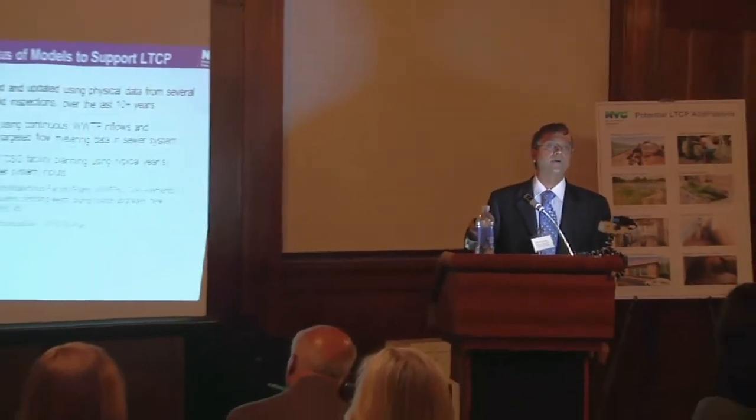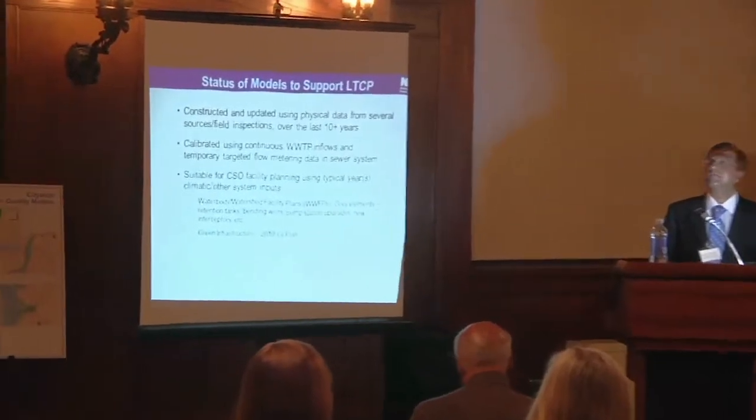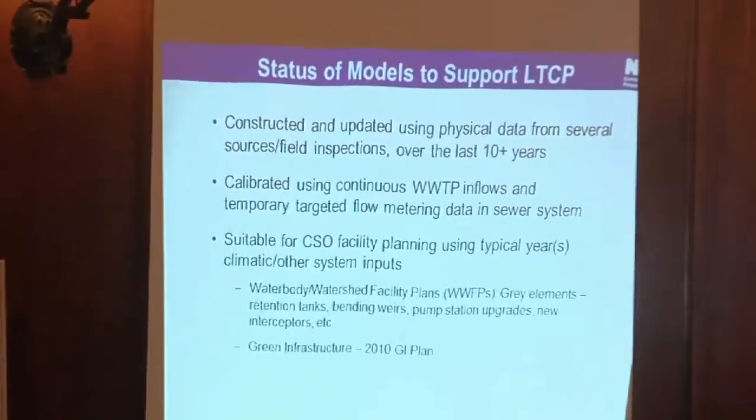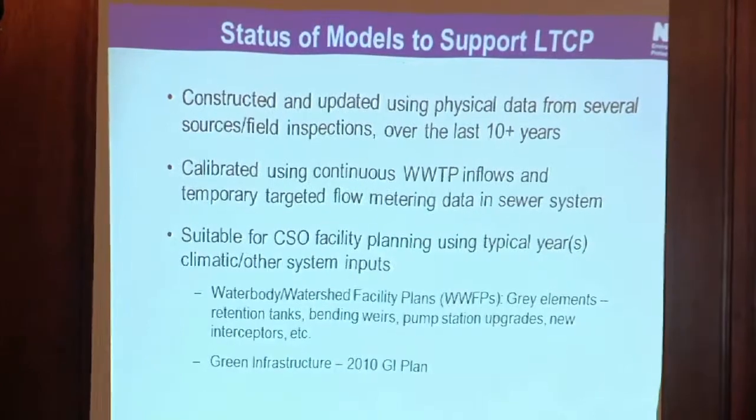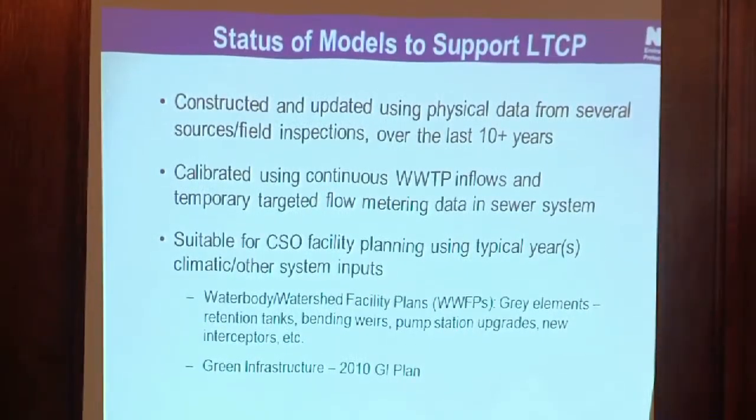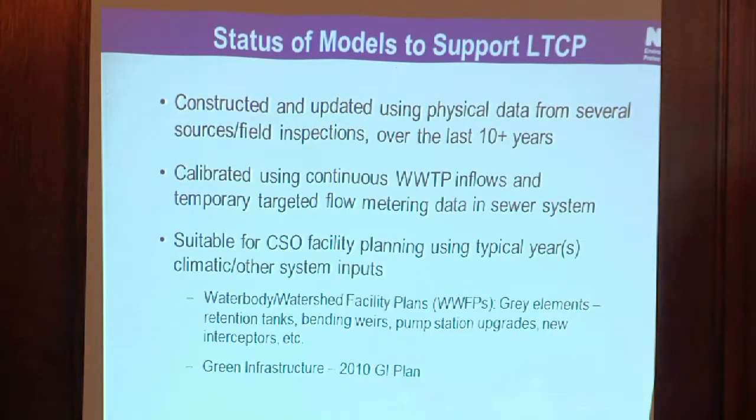The status of the models, as of a couple of years ago: we constructed and updated them using the physical data that we have collected during different projects over the last 10 plus years. These have been calibrated based on the plant inflows. We have hourly plant flows coming into each of the treatment plants, and they are tracked. We also have temporary monitoring that has been done in every one of our drainage areas to support various projects. These are at a planning level, very suitable for doing the CSO control planning.